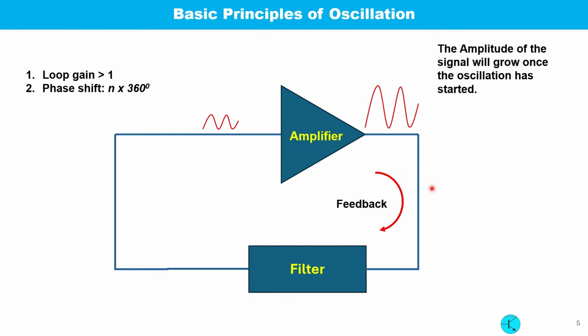We can make an oscillator using an amplifier easily by feeding back the output of the amplifier to the input. However, two conditions should be met. The loop gain must be greater than unity, and the phase angle between the input and the output should be 0 degree, 360 degrees or multiples of 360 degrees, so that the signal not only will be amplified but also grow additively.